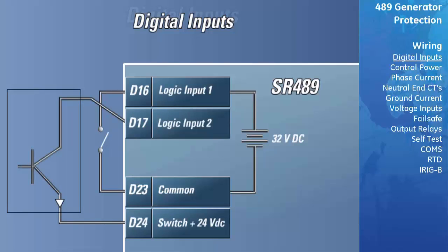There is also a 24-volt DC switch supply provided. This will provide control power for inductive or capacitive proximity switches. The NPN output of the proximity switch can be connected to any of the 4 assignable digital inputs configured as a counter or tachometer. The maximum allowable current draw for the plus 24-volt DC switch supply is 20 milliamps.